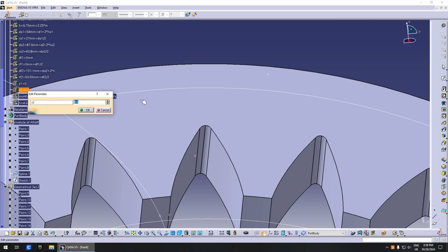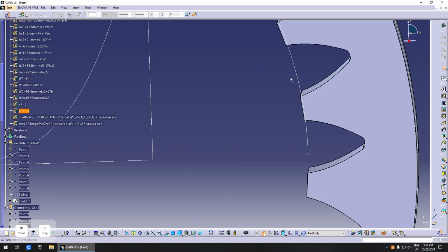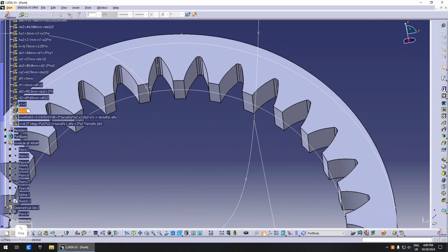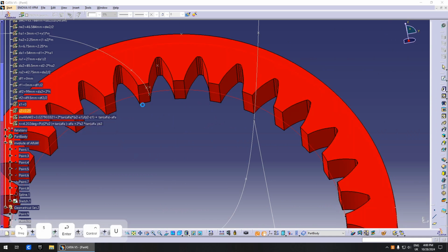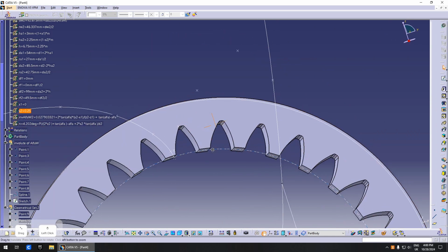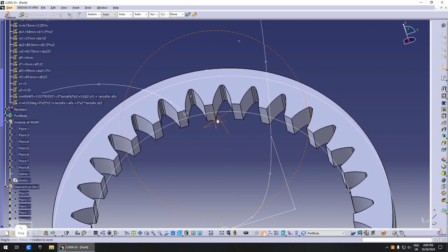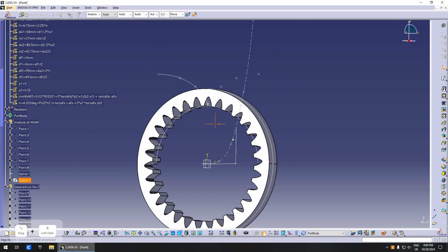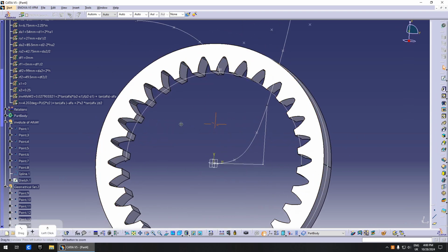So this is how it looks like with 0.6 profile shift. This can actually be lower. I'm guessing 0.5 was a bit excessive on this gear. So 0.25 looks a lot better on this gear, actually. And it should pretty much mesh much better to the other ones.